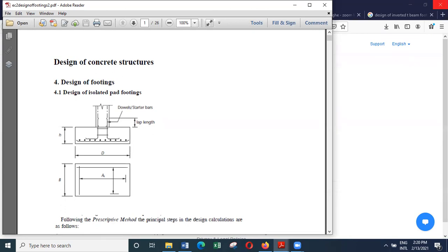And the crack controlling rules have been derived for 0.2 millimeter, 0.3 millimeter, and 0.4 millimeter crack widths. And those values are given as table 7.2 in Eurocode 2. And what I have shown earlier is only an extract because we are interested only in 0.3 millimeter crack width.